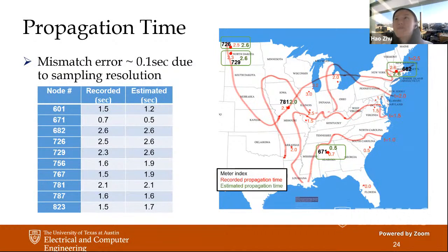But what is worrisome is that in the meantime, there may be some other triggering events, especially if that couples with some transmission lines going out of service, or some transmission lines having a stability issue, a local issue, and then being disconnected from the system. That kind of triggering event is more worrisome because it will lead to power redistribution to other transmission lines and lead to overheating.